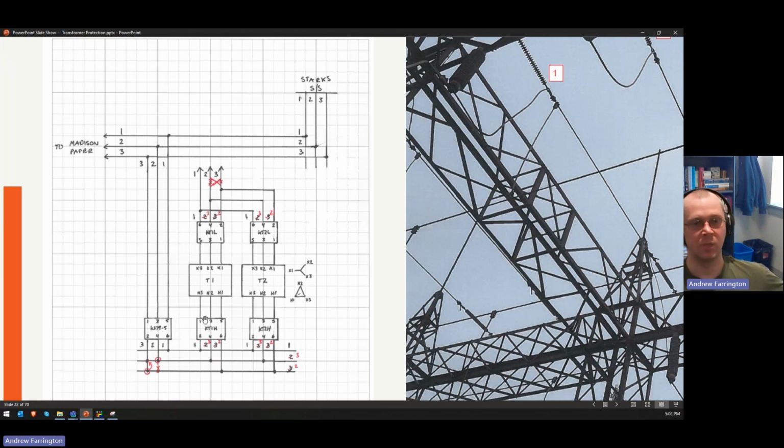So it didn't work. What me and Bill did, we went to the closest utility substation because we could see the phases. They had their phases marked and we could see them from the road. So we took a picture and then we walked the transmission line to the municipality. It was miles long, but we wanted to make sure that there were no weird taps or anything that changed the phases between there and that substation.